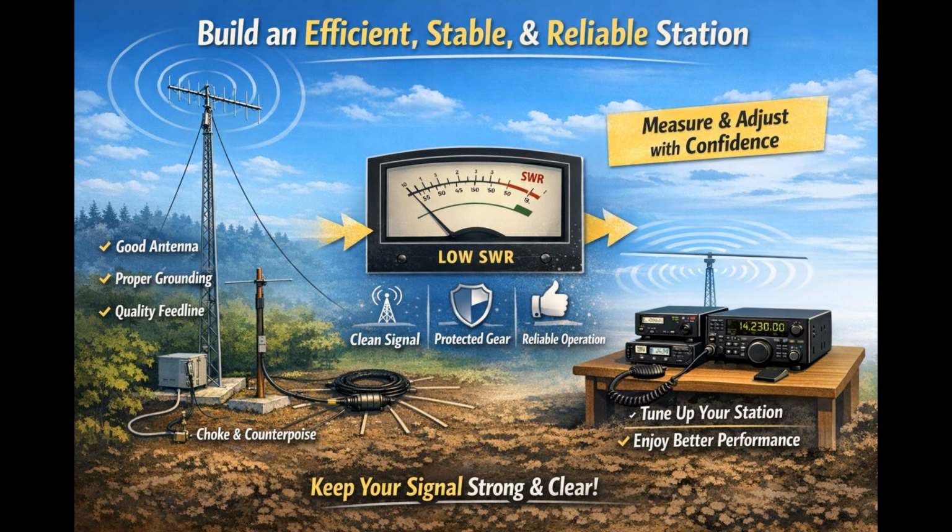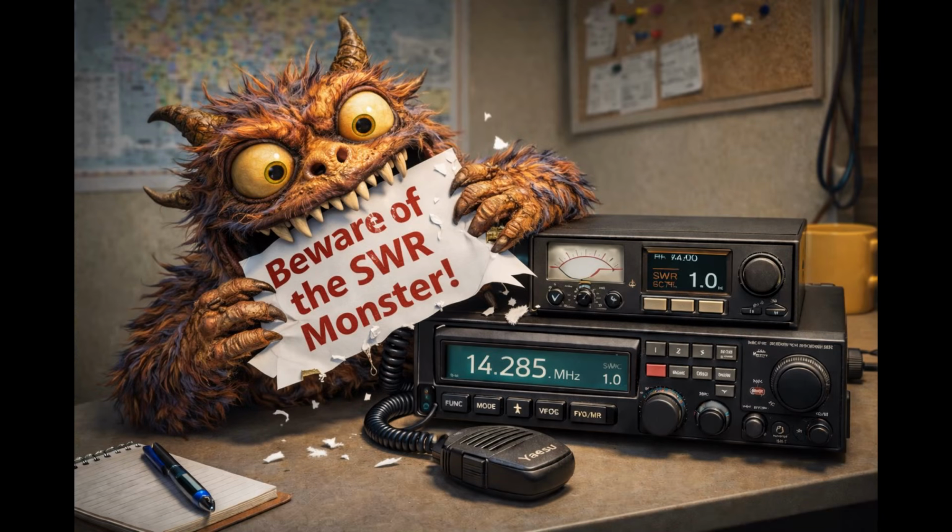In wrapping this up, understanding SWR isn't about chasing a perfect number. It's about understanding what your station is telling you. When you know how radio waves form, how energy moves, and how your antenna system accepts or rejects that energy, SWR becomes a simple diagnostic tool instead of a mystery. By paying attention to your antenna, feed line, grounding, counterpoise, and chokes, you're not just lowering a meter reading, you're building a station that is efficient, stable, and predictable. Because when your antenna system is working properly, your signal gets out cleanly, your equipment stays protected, and amateur radio becomes more enjoyable and more reliable.